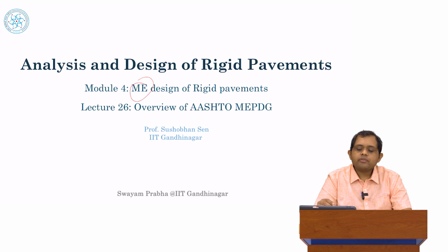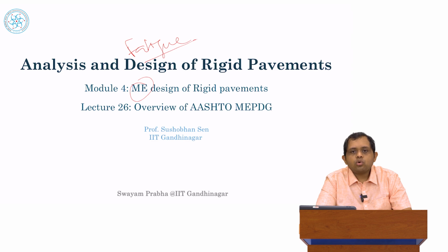In the previous lecture, we went through the concept of fatigue theory. Fatigue theory says that when you apply a load onto a structure such that the stresses developed are much less than the maximum allowable stresses, even then a small amount of what we call damage takes place.